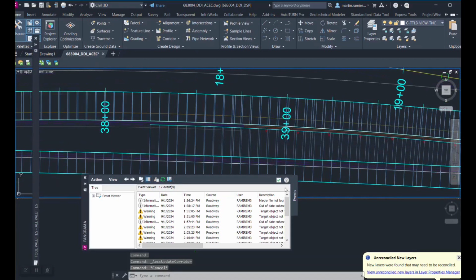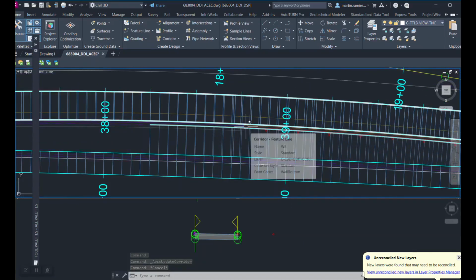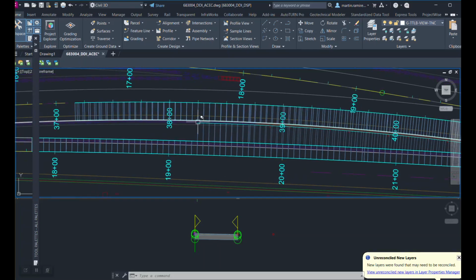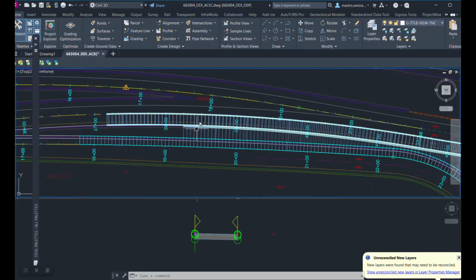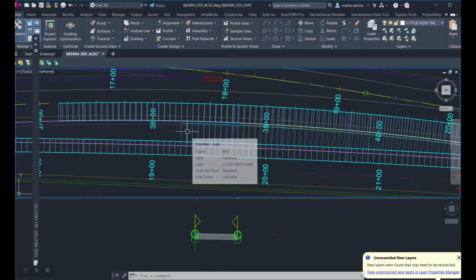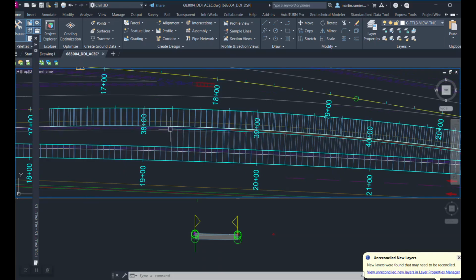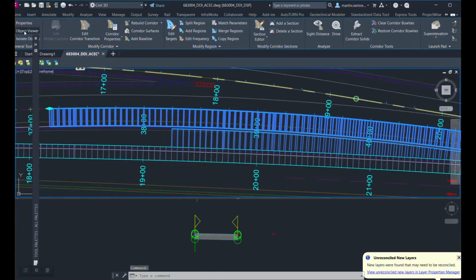Okay, so you can see that with 7 feet, the profile for both roadways stayed the same. The only reason this got longer was that it's getting longer for the depth, and so that would tell us that this is working correctly, and that we're able to hit that 7 feet depth and then still build the wall up to that point. So we'll take another look at that.